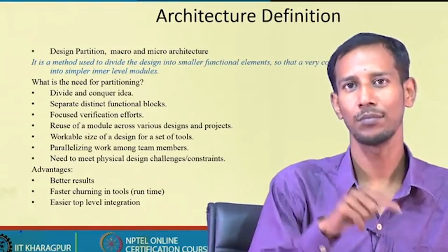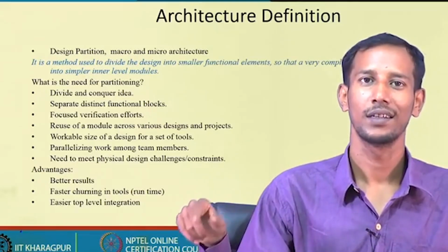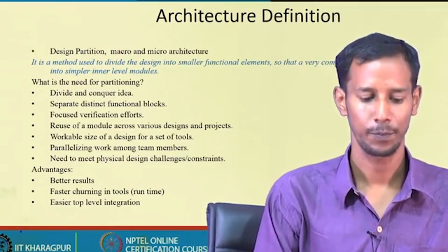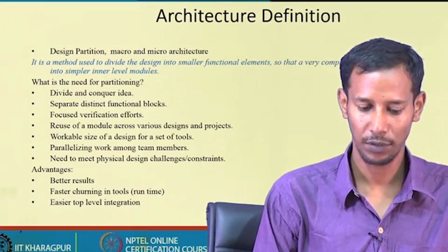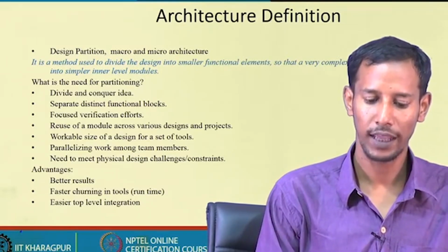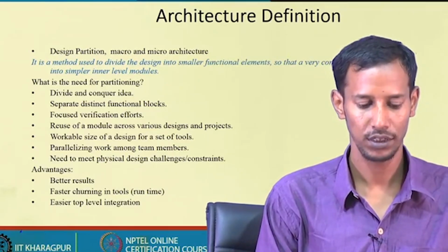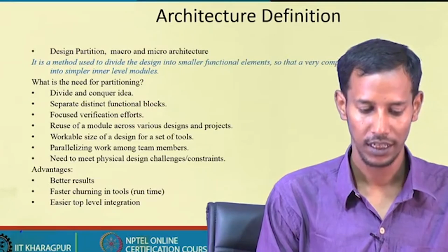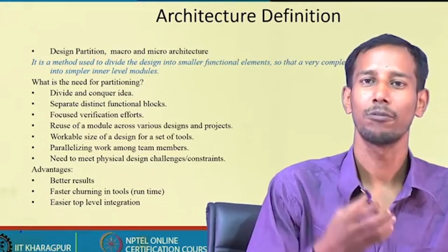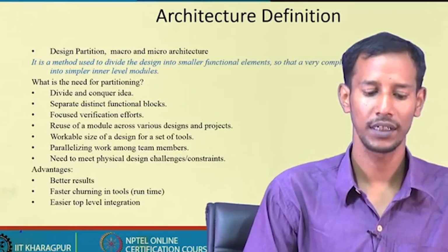So, that means the time for building the particular blocks I can also reduce by simultaneously doing the sub blocks, and separate distinct functional blocks, focused verification efforts, reuse of a module across various designs and projects, workable size of a design for a set of tools, parallelizing work among team members, need to meet physical design challenges and constraints. So, you see there are several advantages of doing the partitioning.